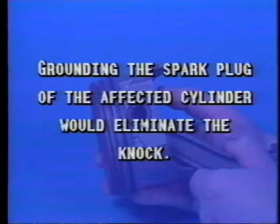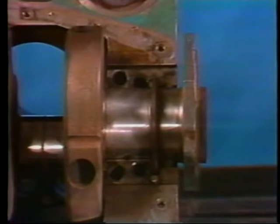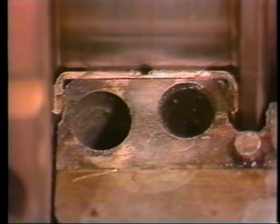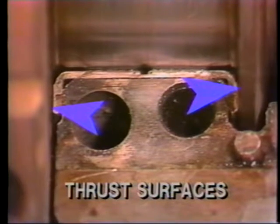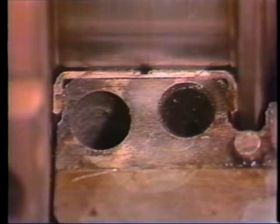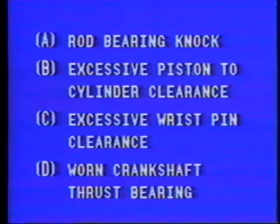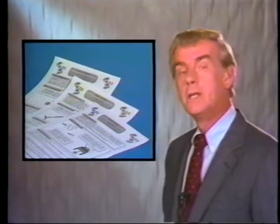The crankshaft thrust bearing keeps the crankshaft from moving end to end. When this bearing develops wear on the thrust surfaces of the bearing, the crankshaft can move end to end, creating a noise. When the clutch pedal is depressed, it prevents the crankshaft from moving, thus eliminating the knocking noise. The correct answer is D, worn crankshaft thrust bearing. Check your task sheet for other noise prints of failed internal engine components.